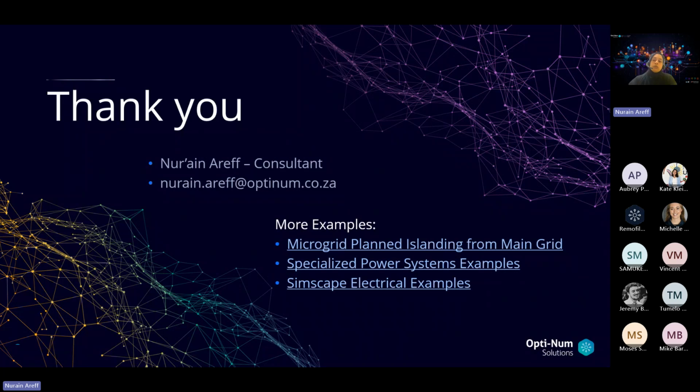It's not included within this demo, but we can have more discussions on that. What is included in this demo is that we sized our components, which were our PV as well as our battery, to ensure that we use as little grid as possible, while also at some points feeding back to the grid, so we ensure maximum cost savings. That is what happened in the demo.